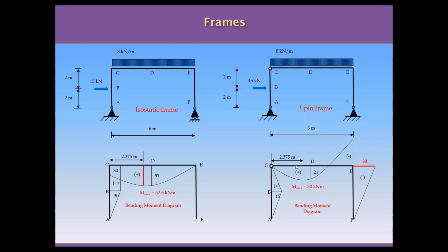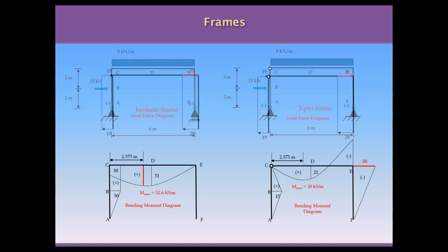So again, it is important to understand that the modifications in the restrictions we introduce to our structures, and of course the load we apply to our structure, will produce changes in the distribution of internal forces and the distribution of stresses. And this is because we are changing basically the reactions, and because we change the reactions, we are going to change the internal forces and the stresses. So this was the comparison between these two structures.